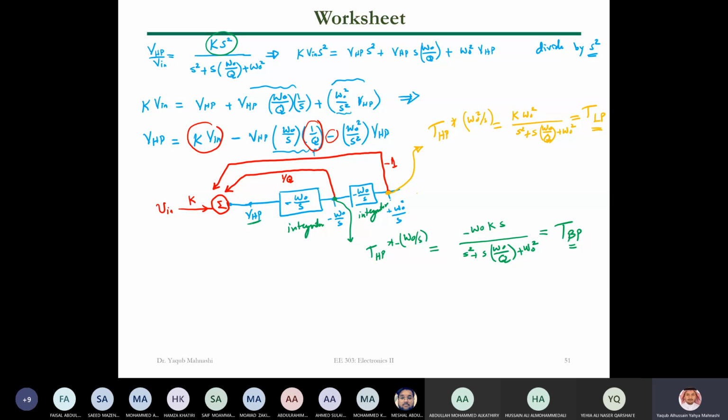So you have, guys, one filter topology, or one circuit, from which came out high pass, low pass, and band pass. Okay, so it is a truly universal filter. And we know, guys, of course, if we have a band pass filter, we can find an all pass filter. We derived it before. All pass from the high pass, sorry, from the band pass is a constant minus the band pass. So this is the case. All pass is nothing but constant minus band pass filter. So if you can apply some constant here and subtract it from the output of the band pass filter, you are getting an all pass filter. You can do the same with the notch and everything else.